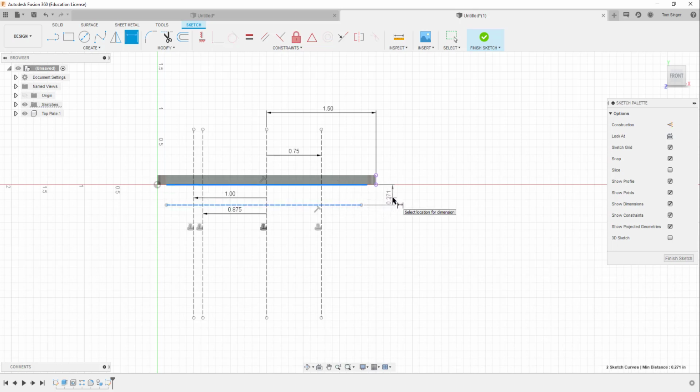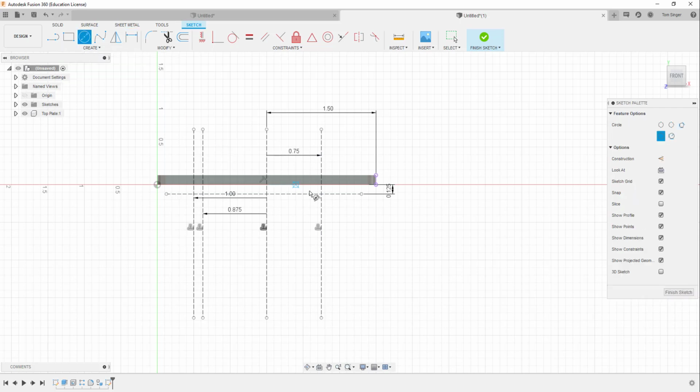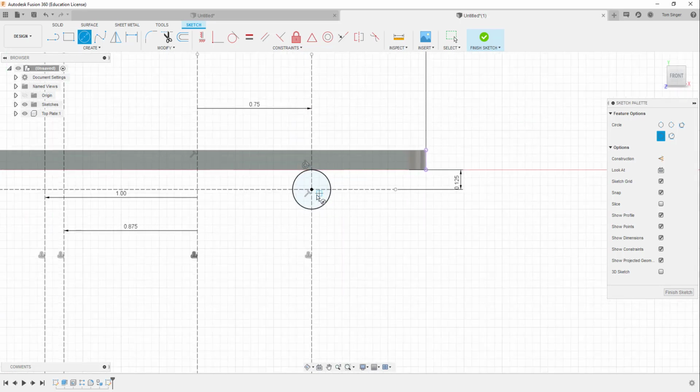That dimension is going to be 0.125. And that's because we're going to be creating 1/4 inch circles as placeholders for our arcs, as tangency locations. So we're going to create a circle at this location, this intersection, and it's going to be a 1/4 inch total, which, by the way, here to here is a 1/8 inch, so we double it, it's a 1/4.